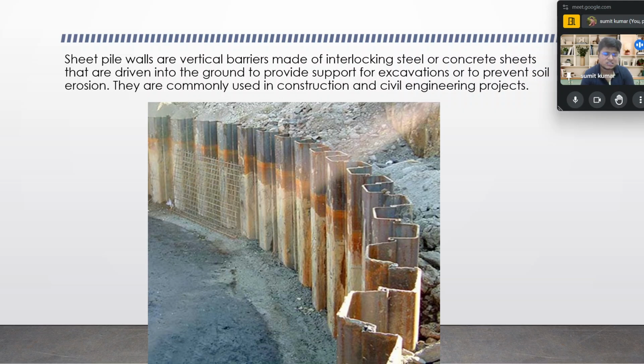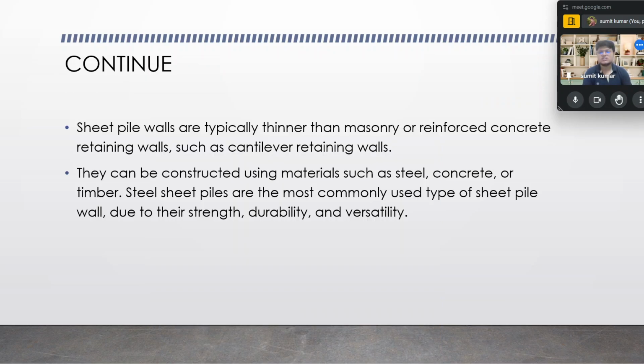If you come across a place where bridge construction is going on, specifically in a river plain, inside the water. Sheet pile walls are typically thinner than masonry or reinforced concrete retaining walls, such as the cantilever retaining wall, and they can be constructed using materials such as steel. If they are constructed with steel, they are very easy to dismantle as well.